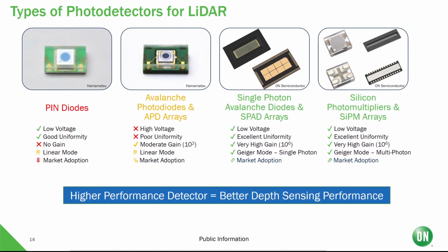Why use SiPM for LiDAR rather than another photodiode? So PIN diodes have been around for a long time and do a good job of detecting photons. However, the low gain of the PIN diode means that it is not a suitable detector for long range, where the return signal power level is low, since the photocurrent signal can't be detected at low optical flux.